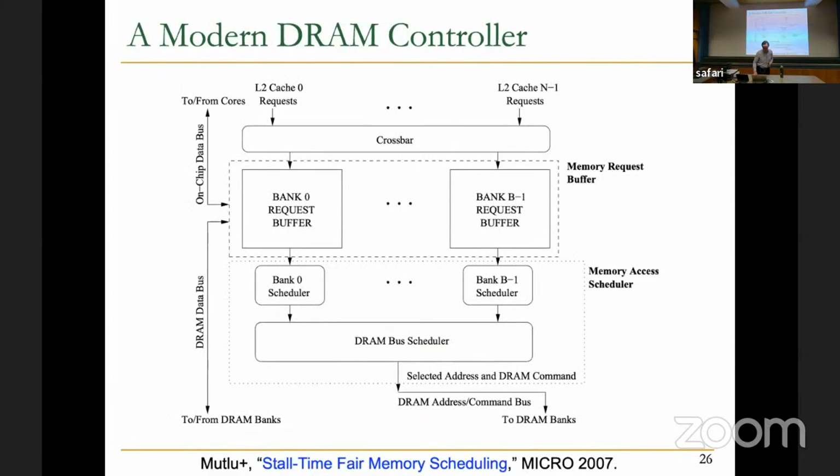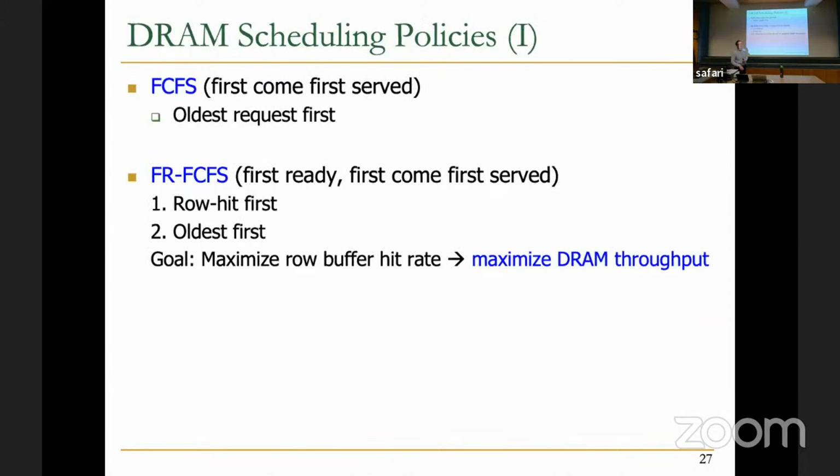Okay. In the past, there used to be FCFS controllers, like first come, first serve. This is like old Pentium 4, I think. I mean, even Pentium 4 had FCFS, actually. Pentium Pro had FCFS controllers. This also shows you how memory and processors evolved, right? There were these complicated techniques to do out-of-order scheduling in the processor chips. But in the memory chips, people said for a long time, memory controller chips, I should say, let's do first come, first serve.